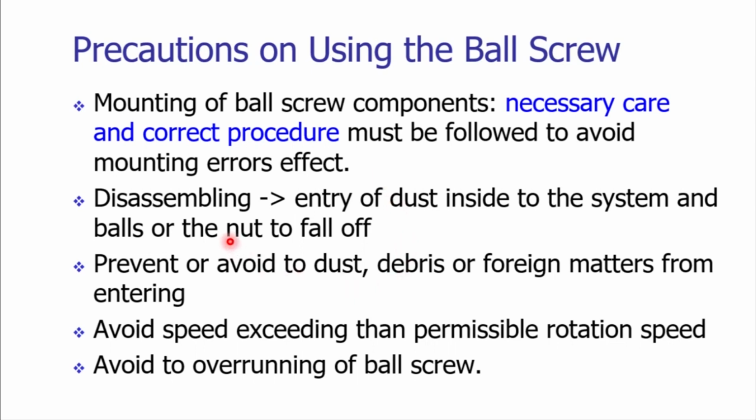During disassembly, we need to avoid the entry of dust inside the system, because we need to have very less friction. If the dust particles are there, that may increase the friction. In addition to the dust, we should avoid debris or foreign matter entering inside the screw and nut assembly.